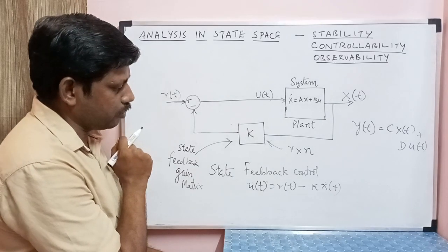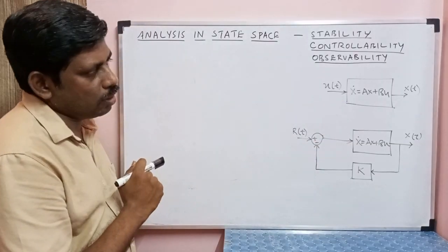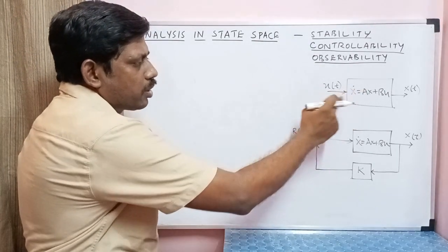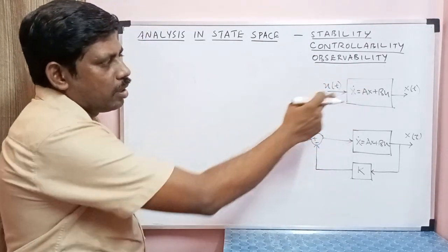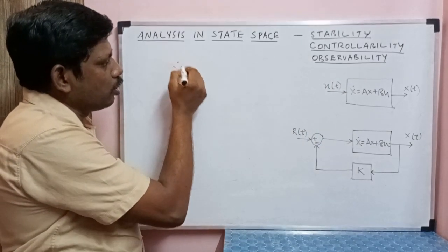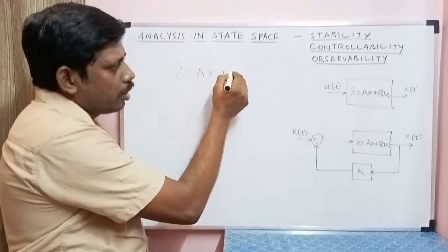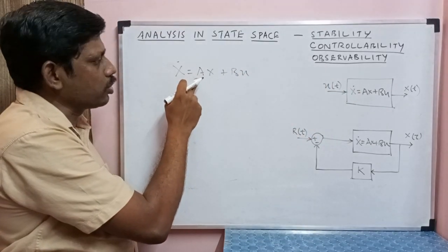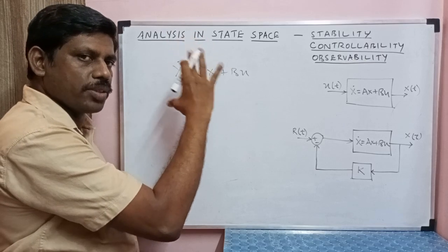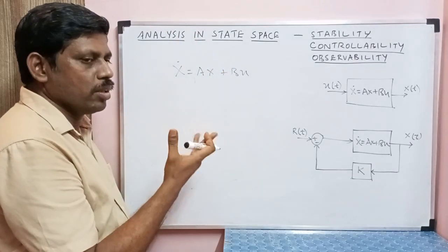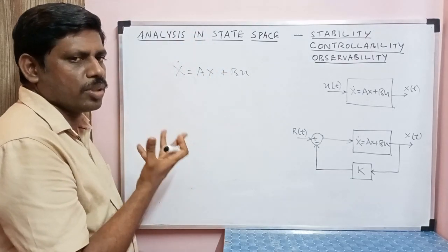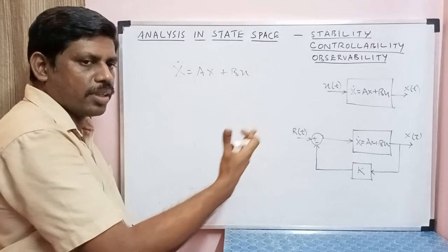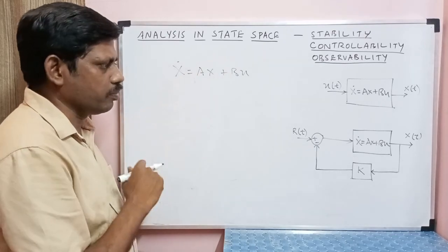to be analyzed. This is the system without the state feedback, and the state matrix for this system is A. Its input is u, and the eigenvalues can be obtained from this state matrix, and I will have a set of eigenvalues. So let us assume that I'm not satisfied with these eigenvalues, because maybe one of the eigenvalues is on the right side and the system is unstable or something.